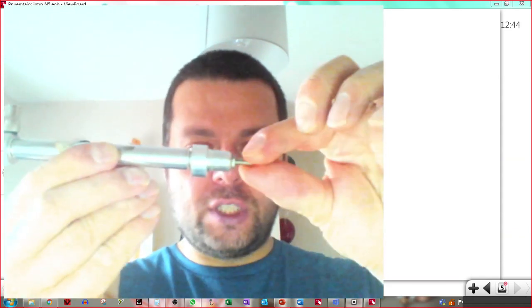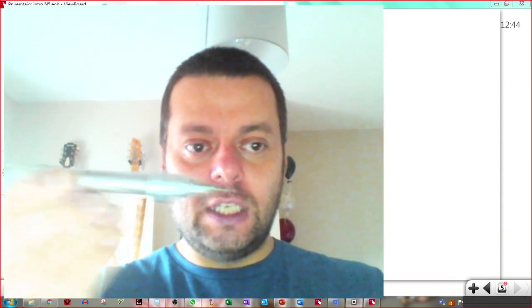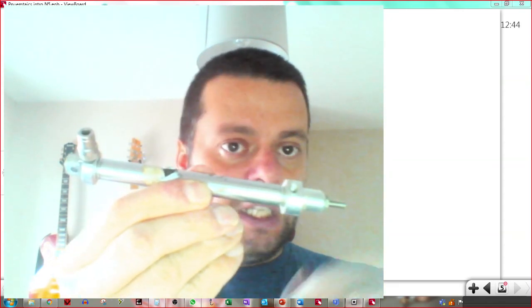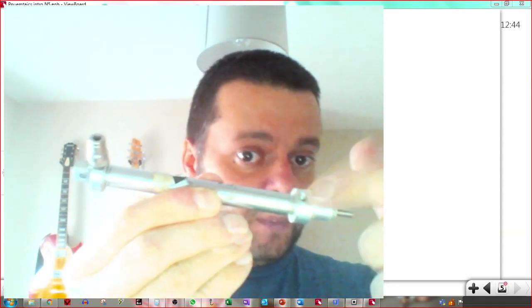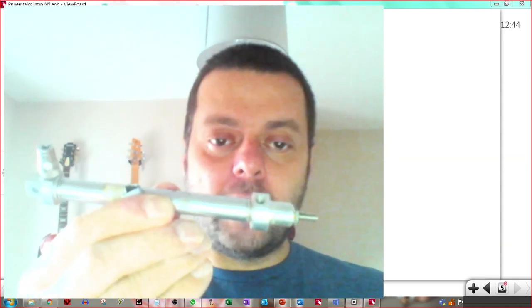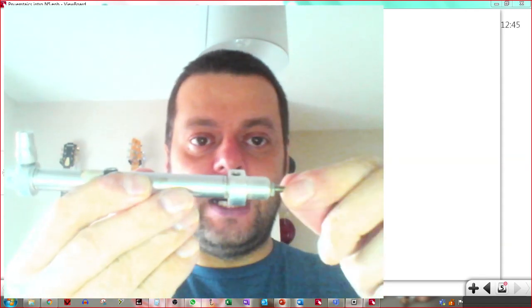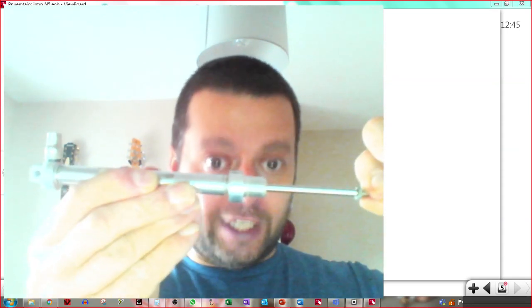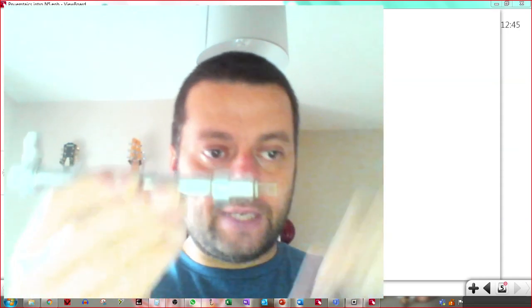There's the piston rod sticking out. It's currently in-stroked, obviously. You can see the port on the back end of it where we would plug the hose in. You can see an empty hole in the front because obviously there's still air inside that cylinder that would have to come out whenever we outstroke it. So you can see that if I were to put air in there, the piston rod would come out that way. And if I let it go, it springs back in.